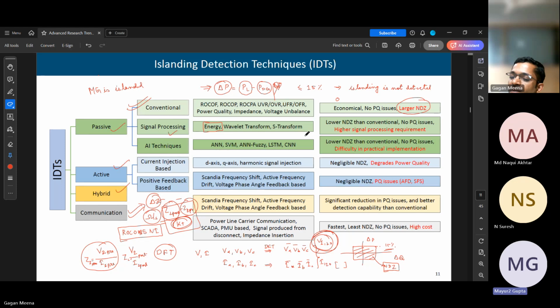As you said, communication-based systems have all-digital circuit breaker communication and all that. It is good, but it has a time delay, and that time delay ultimately leads to load shedding in the microgrid, because there is no time left, or the frequency starts dipping, or there may be a blackout in the microgrid if we wait till that time and then don't do load shedding. So you should have a backup for communication schemes also.